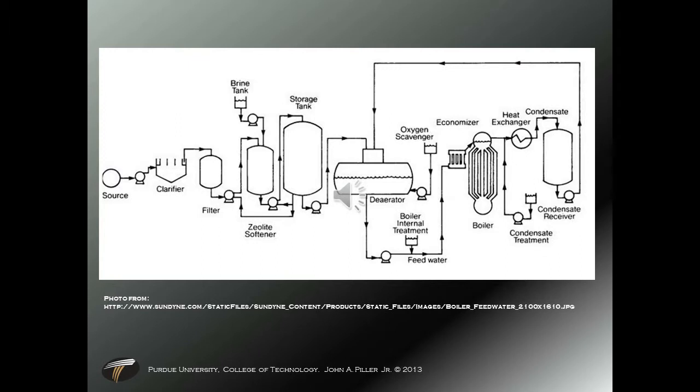Other auxiliary systems of note on this drawing, the economizer. On the left side of the boiler, there is that 4-columned looking Roman structure. That schematic is designed to talk about the economizer. It's a heat exchanger that sits within the flue of the combustion material that we're using to heat the boiler. We put it in the flue to preheat the water going into the boiler. It's a capability of improving efficiency.